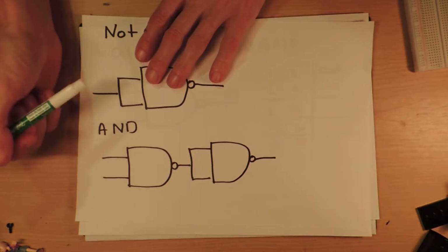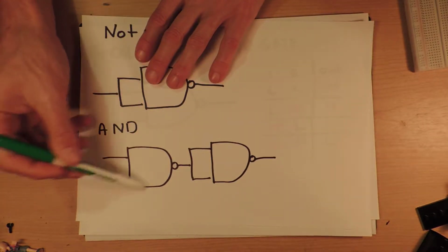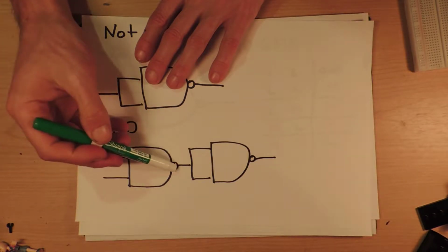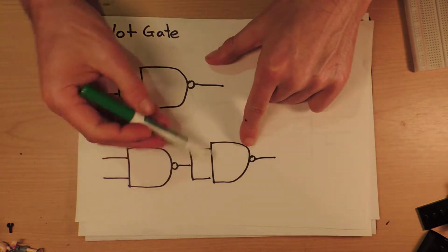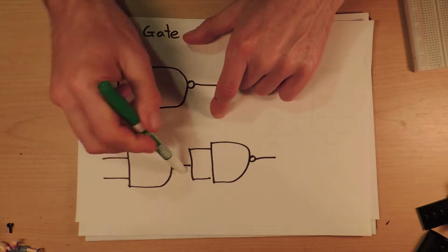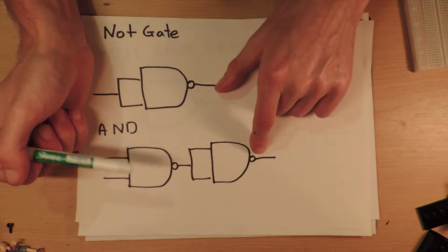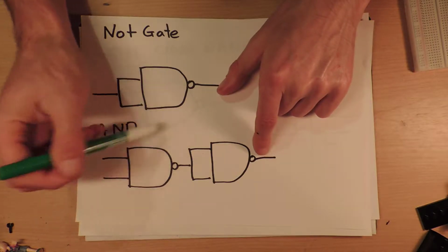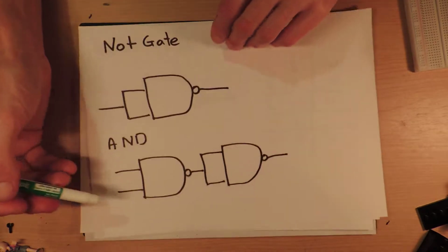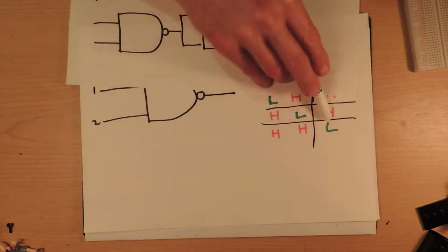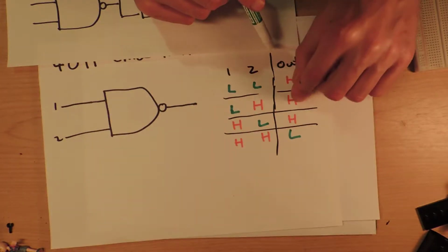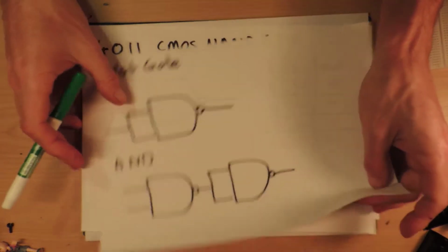But you could also make an AND gate out of it by putting 2 of them together. So if you take your NAND, and now it's giving an inverted output from what the AND would get, then all you have to do is put it through another inverter, or another NOT gate. I'm going to call them inverters, it makes more sense. I'm going to invert the output, and you basically get an AND gate. So if you get a low output from this, it's going to be a high output in the end. So it's just going to flip these around. These are going to become low, low, low, and high, which is an AND gate. So you've made an AND gate.